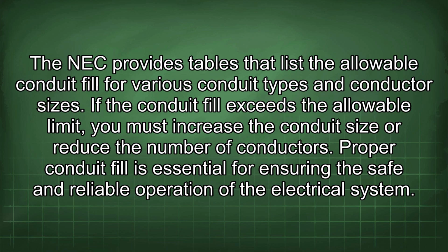The NEC provides tables that list the allowable conduit fill for various conduit types and conductor sizes. If the conduit fill exceeds the allowable limit, you must increase the conduit size or reduce the number of conductors. Proper conduit fill is essential for ensuring the safe and reliable operation of the electrical system.